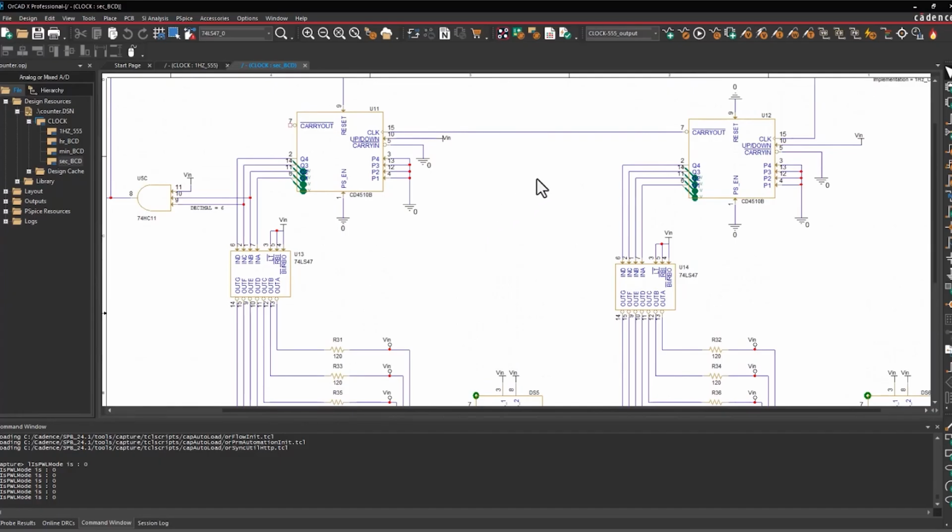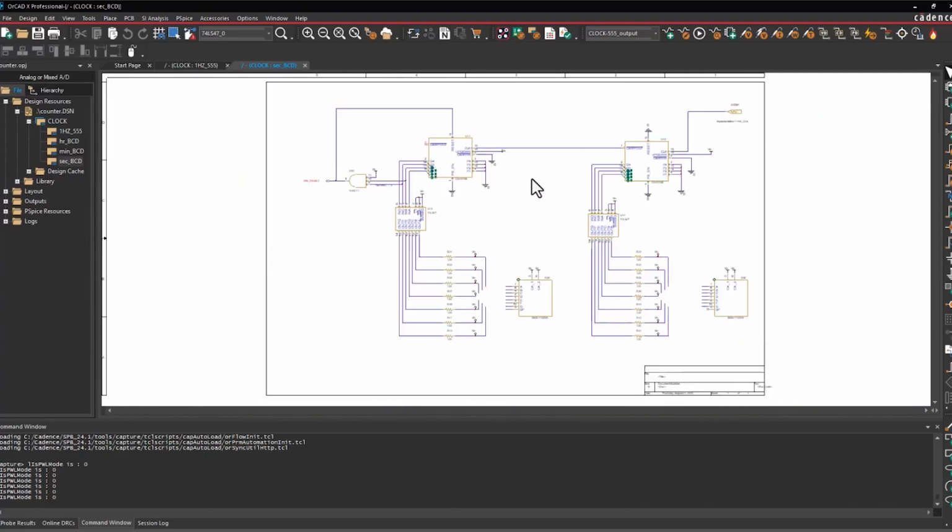What I really wanted to make sure is, were my counters keeping track of the time correctly? For this test, here to the right, U12 is my 0 through 9 counter and should be counting from 0 to 9 seconds. And at 10 seconds, this should be set to 1. And U11 should be counting from 1 to 6 and then resetting with how I have my AND gate connected to it. Then this seconds circuit is fed into my minutes, and similar for my hours.